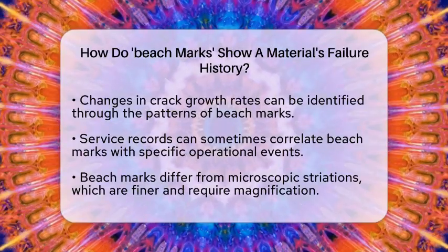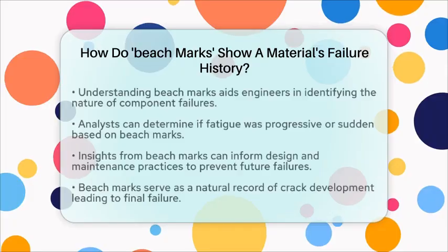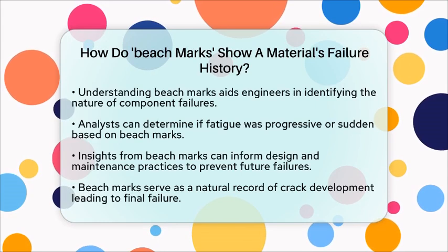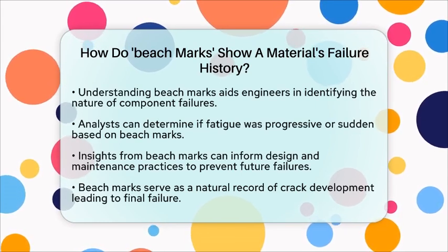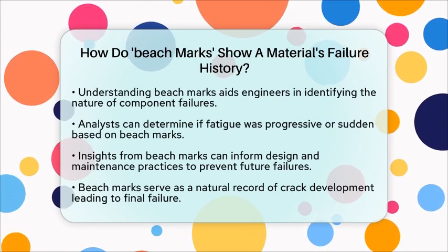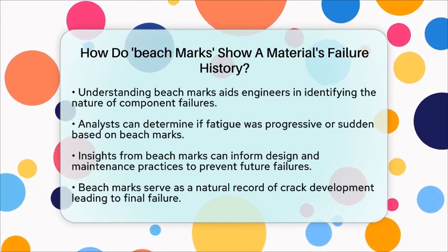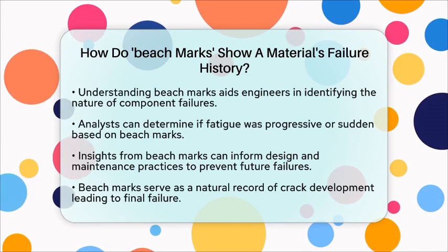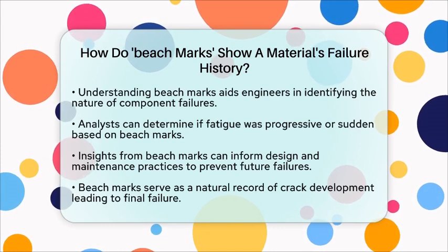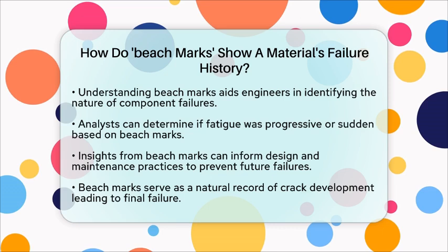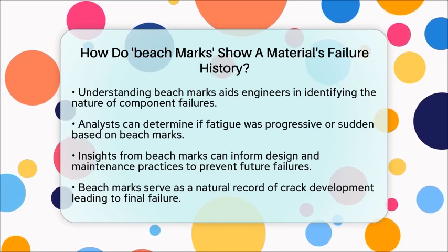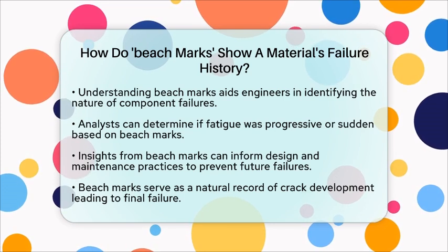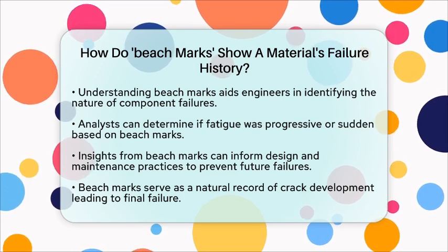It helps them identify how and why a component failed. They can determine whether the fatigue was progressive, meaning it developed over time, or sudden, indicating a rapid failure. This knowledge can also help assess whether operational changes or environmental factors contributed to the crack growth. By examining beach marks, engineers can improve design and maintenance practices to prevent similar failures in the future.